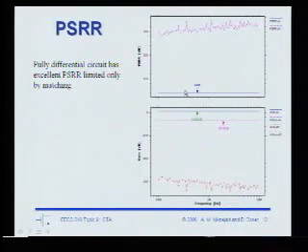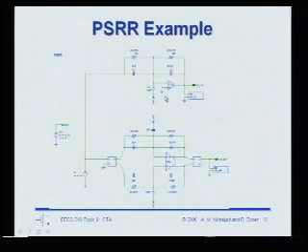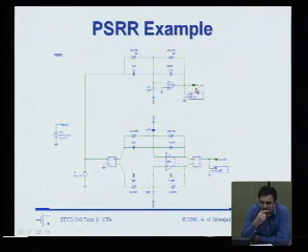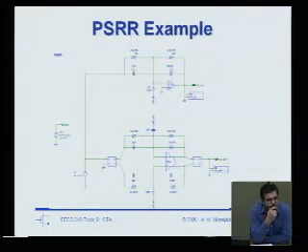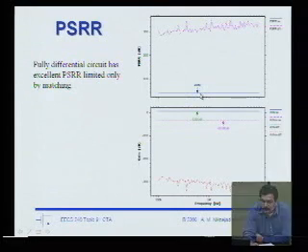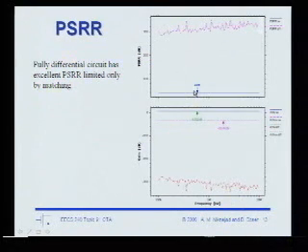So first of all, interesting, what's the power supply rejection of the first circuit? So in this first circuit, if I vary the power supply, VDD, I'm seeing a signal at the output. Does that make sense to you guys? What's going on? What's the probable cause of this finite power supply rejection ratio? It's only 40 dB, right? 40 dB is not so much.